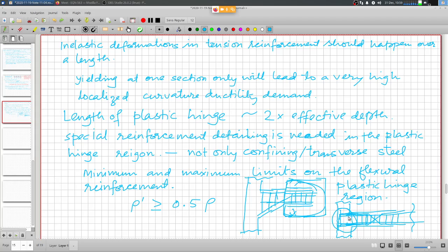And when this yielding penetrates into this beam column junction, that may lead to deterioration of the bond strength. Obviously, there are compatibility issues. I mean, there are more deformations, more strain that needs to be countered, and that may weaken the bond, and that will affect the shear strength of this beam column junction, and that will be very, very critical.